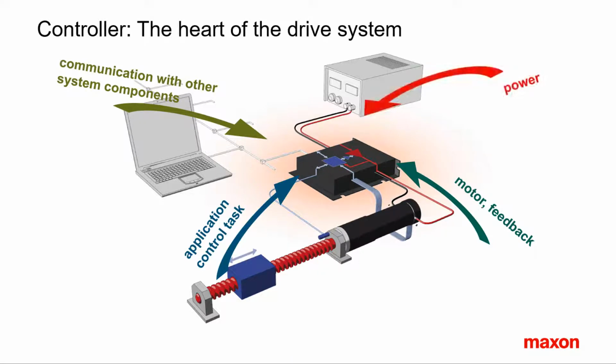The controller should be adapted to the supply voltage range and be able to handle the required electrical currents. Modern controllers are quite versatile concerning motor and encoder types, communication and operation modes. This requires proper setup or configuration.